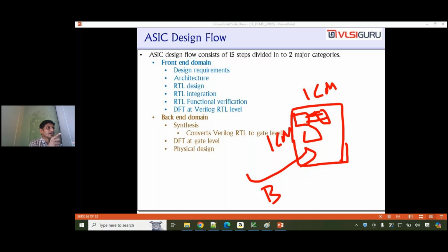Every block has to get a reset logic. Every flip-flop has to get a clock. So the whole concept of physical design gets complicated there, because they have to place hundreds or thousands of macros, the blocks, and a lot of standard cells, and for all of them they have to do the connections, which makes it complex. So that is where the entire backend flow is driven by software.